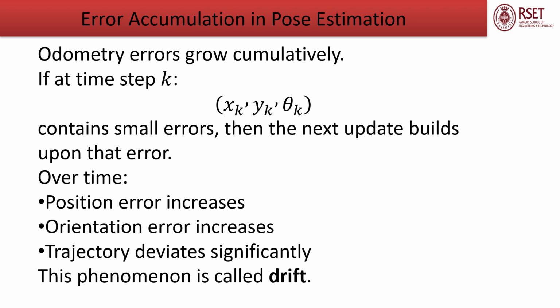This slide conceptually illustrates how error grows over time. Initially, position estimation may be very close to actual position, but as time progresses, uncertainty spreads. Think of it like drawing a circle repeatedly with slight hand movement error. The deviation increases gradually. In robotics, this uncertainty can be mathematically represented using covariance matrices. The longer the robot moves without correction, the larger the uncertainty region becomes.